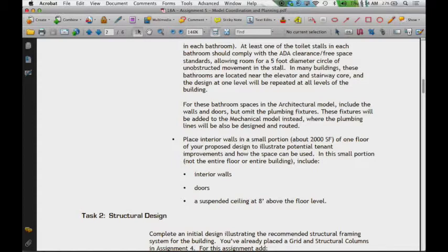The idea with the bathroom is that typically those end up being near where the stairways and the elevators are, because even if your building does all sorts of swoopy things, the stairs run up vertically, so almost always your restrooms will be able to run up vertically and you'll get a nice riser. You get what I call a stack. They'll tend to be in the center or the core of the building, outside of the range of where the interesting gymnastics are happening.